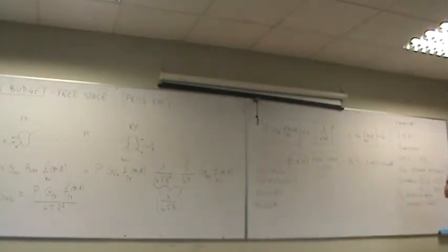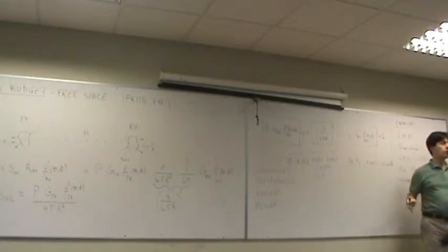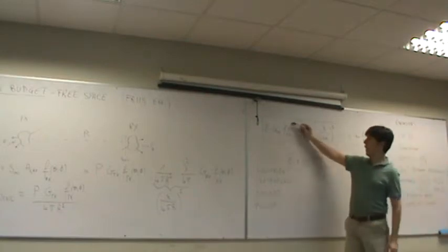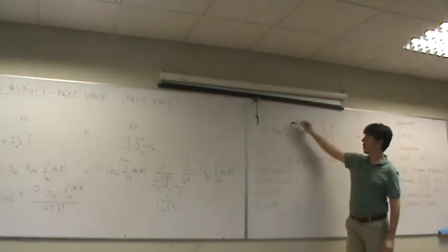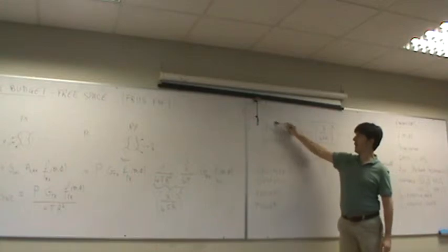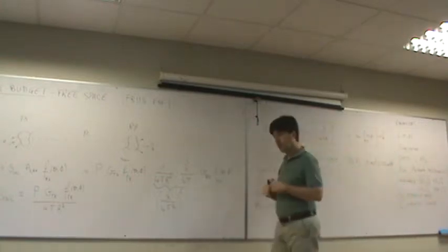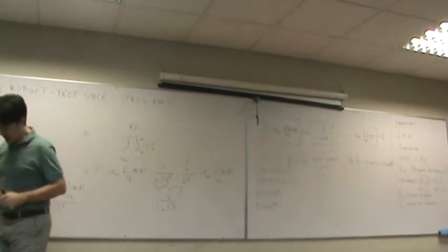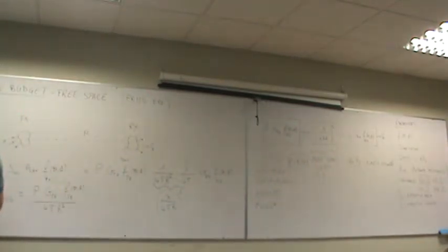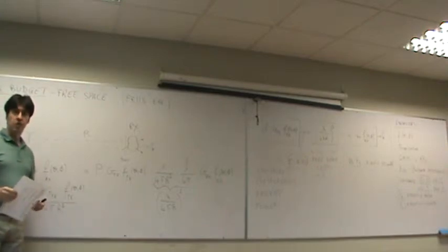Usually you choose for the lowest cost, whichever combination between transmitter power and antenna gain is less expensive, unless you have some specification on the directivity function and then the gain is given. Okay, we will do some exercises on this later on during this course. Okay, questions?